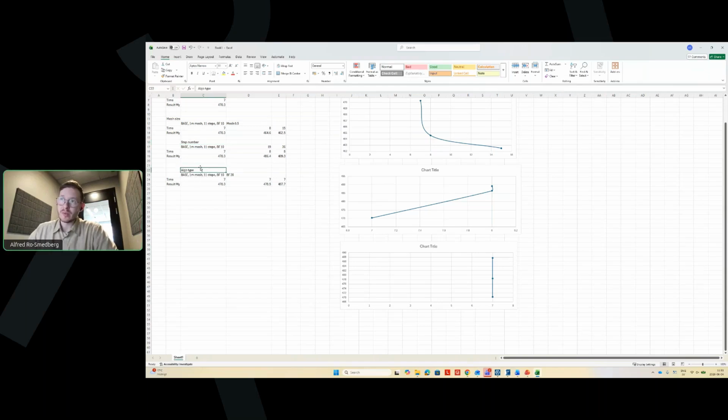The type of algorithm and the number of steps, it's a bit harder to judge also. Generally, it works, like I said. With the multi-start, you can usually find much more accurate results. And I think you can see here that the accuracy jumped up quite a bit, even though we previously used this brute force method for 20 steps, which is a decent amount. We were still only able to get a good detail once we went over to multi-start. But the multi-start usually takes a bit longer to run.